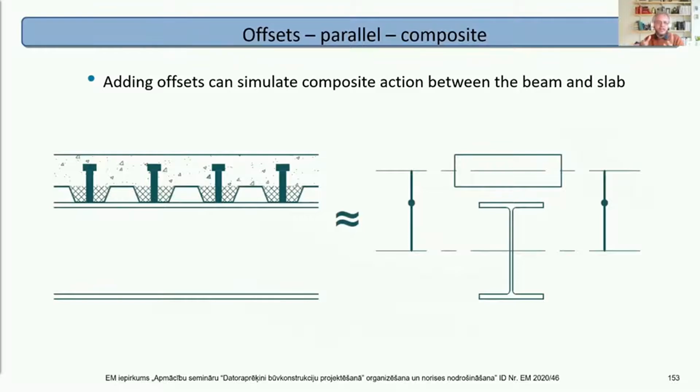Also, when you're modeling the slab and the beam, the engineering structure model is studs in the profile decking troughs. And also these can slip a bit, they can bend a bit, they get partial interaction between the two. That is difficult to achieve in the FE model. In the FE model, we have offsets down, offsets up. These offsets are rigid links, and effectively we've got complete stiffness connection between the two.